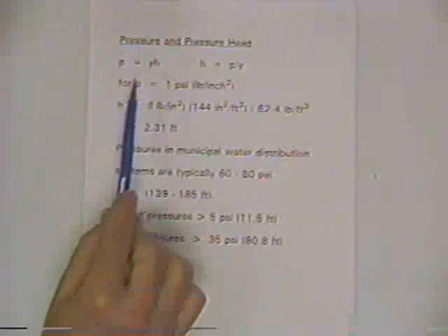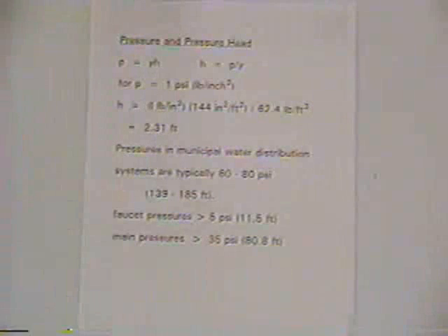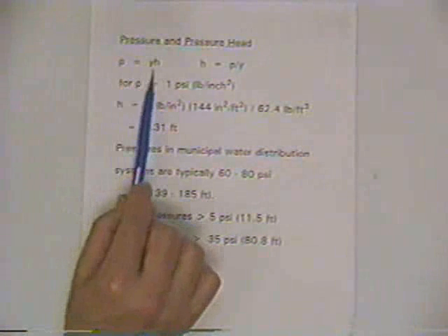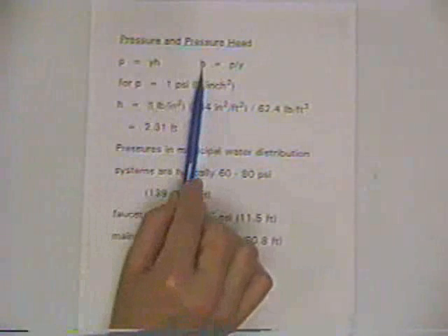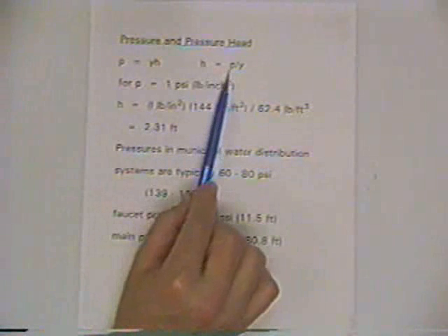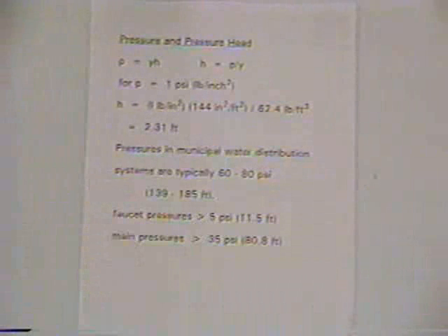And this takes us back to fluid statics. The pressure term is really the hydrostatic pressure distribution term from fluid statics. That, remember, pressure is just gamma times H. And we worked with this equation earlier in fluid statics. Now we express it as a head. The head is the pressure divided by the gamma.